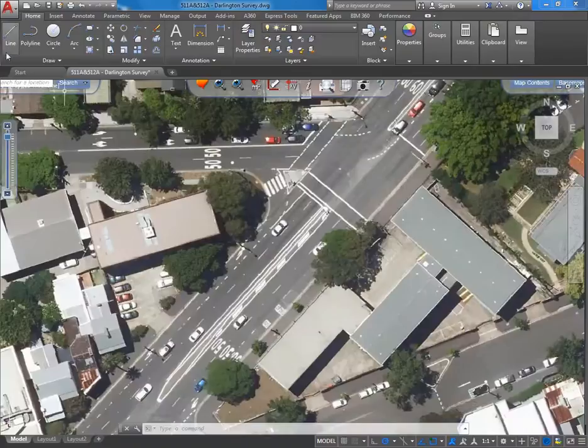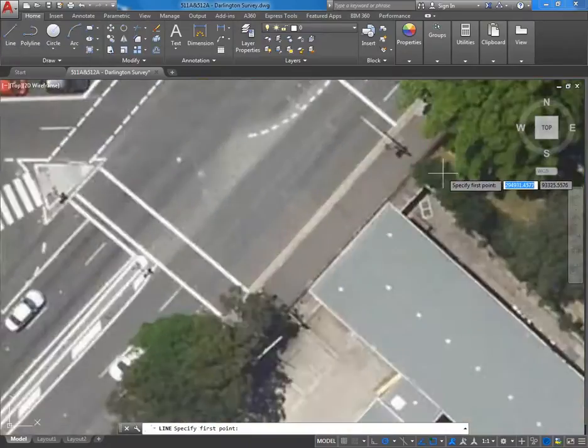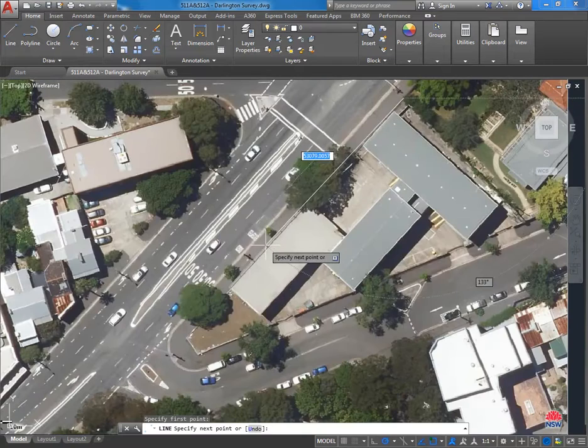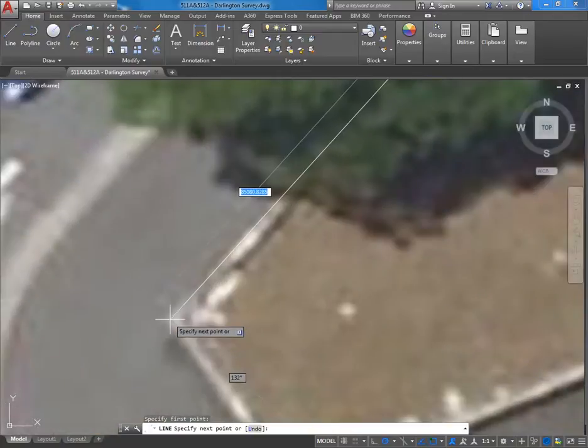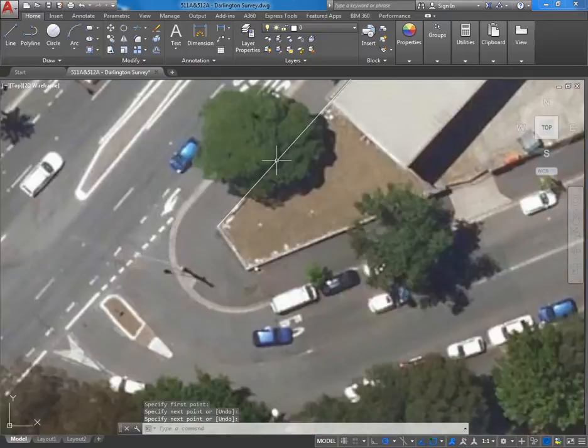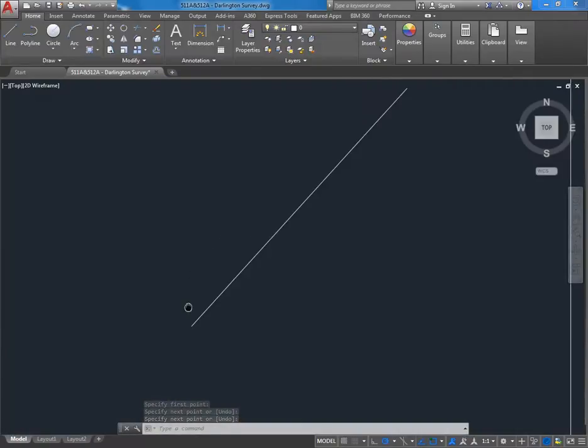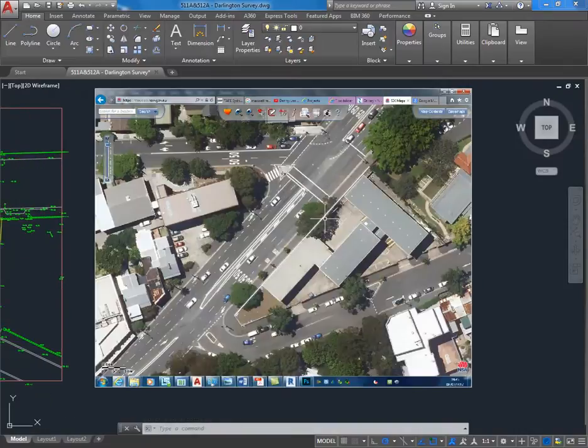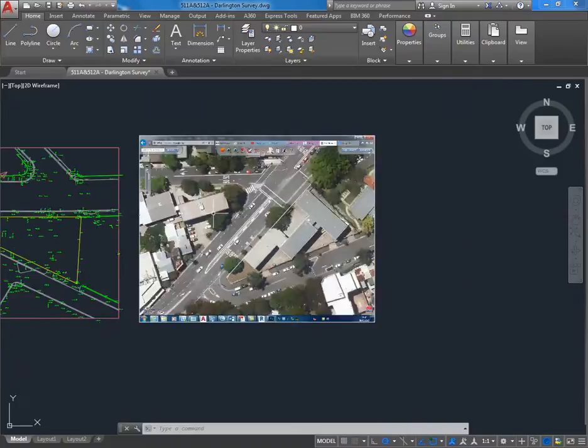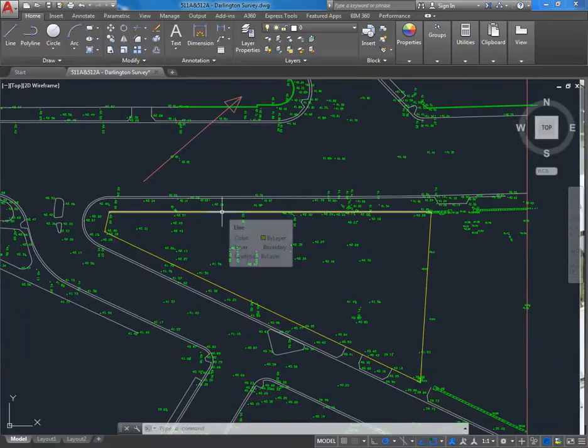Now I'm going to go in and draw a line, just to help me, from the corner here of the site. So the corner of the site's roughly there, so it projects from here to about here. And really what I'm trying to pick up is the angle of that side of the site. So I'm just tracing the fence all the way along there, or the edge of the footpath. And can you see why that is the most important boundary for me to make horizontal? That's because looking at the site drawing here, my walls, the way I've been thinking about the design, my walls will be parallel with that boundary. So I want my plans to read horizontally with that wall being straight, a straight line.